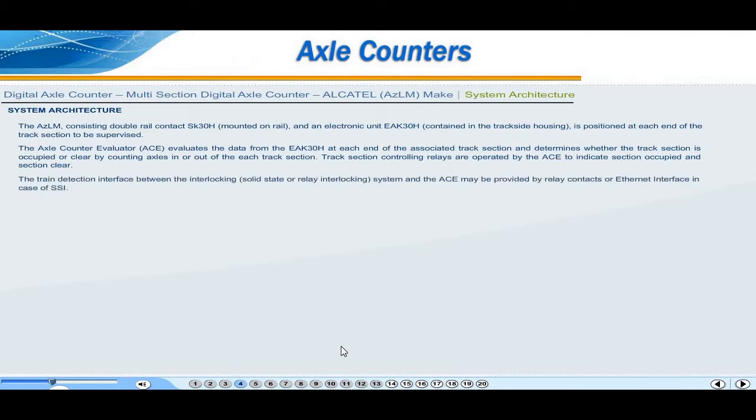The train detection interface between the interlocking, that is solid state or relay interlocking system, and the ACE may be provided by relay contacts, or Ethernet interface in case of SSI. ACE is equipped with diagnostic interface software. An RS-232 serial interface provides communication to a computer.